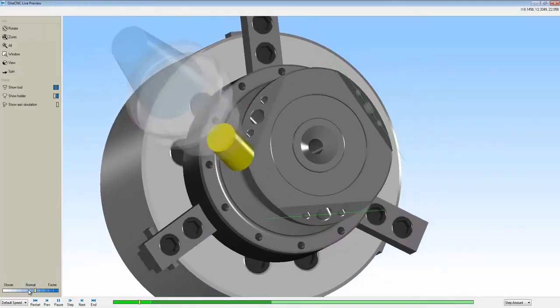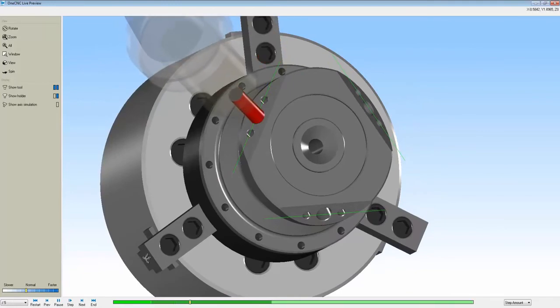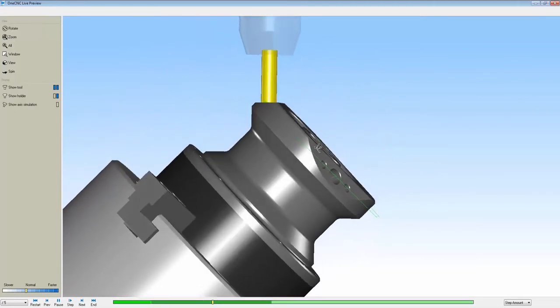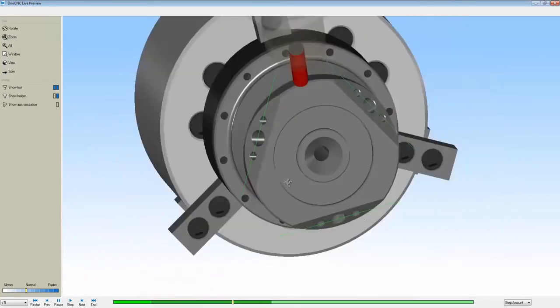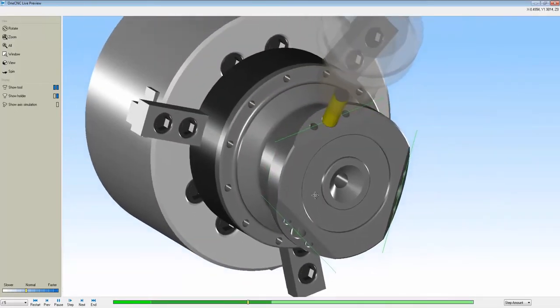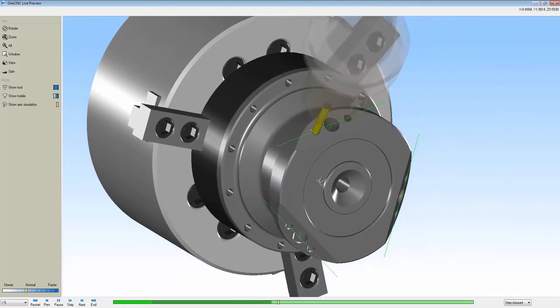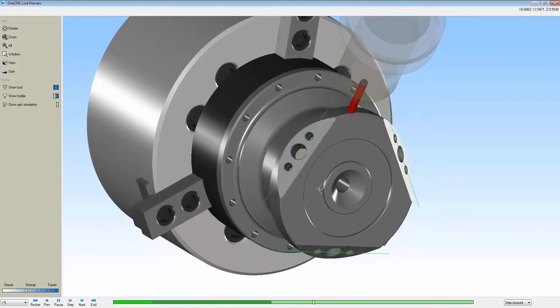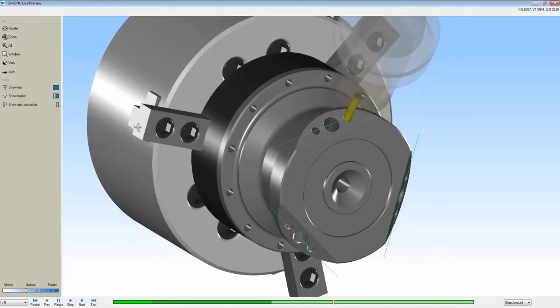Let's slow that down just a little bit. I'm going to change tools to a drill, perform some peck drilling. Notice how the tool is normal to that surface. So that's the benefit of having the B-axis support. Very nice. So we'll switch tools now to a smaller 1/4 inch diameter drill, perform some peck drilling, and then again we'll rotate the part around and machine that. Very nice, very efficient. So there's a nice overview of the OneCNC powerful suite of tools for mill turn applications.